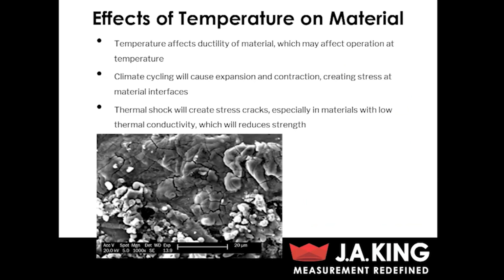Also, climate cycling is going to cause expansion and contraction of your parts, and this can lead to stress, especially at material interfaces. If you think about a part that's got different materials within it, you're going to have parts that are expanding and contracting at different rates, and that's going to impose compression and also tensile and shear forces at those component interfaces.